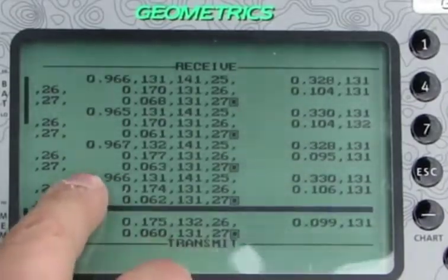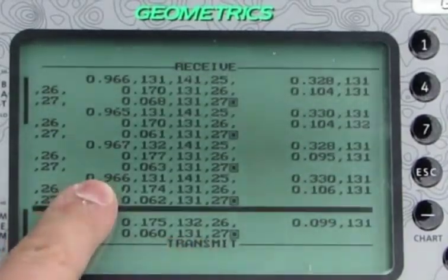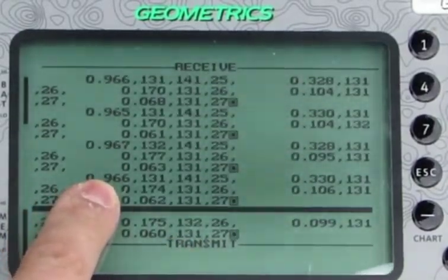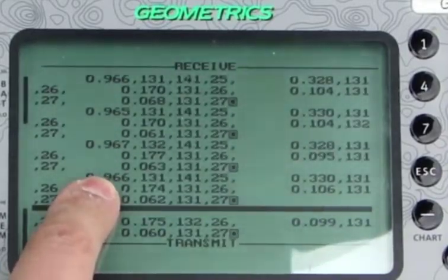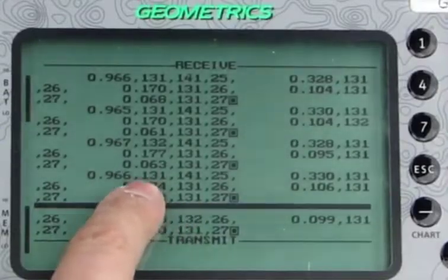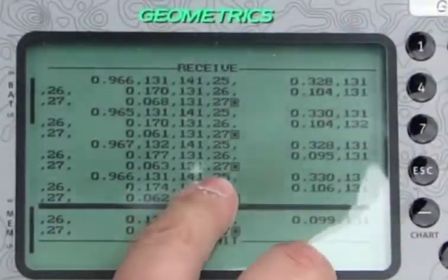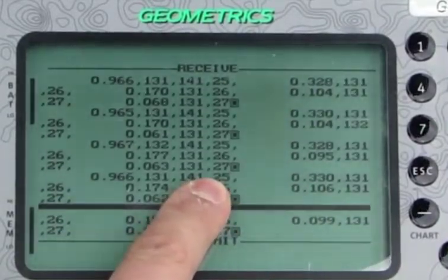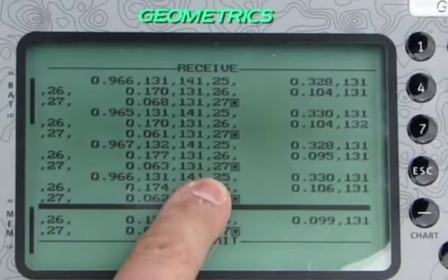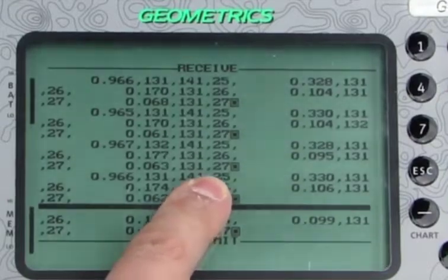The first value here is your actual reading. This is already normalized for volts to current, so this is in microvolts per milliamps. The second and third numbers are your receiver and transmitter battery voltages. The fourth number, which is 2 digits: the first digit is the current level from the transmitter. The second digit is the gain for that particular receiver.